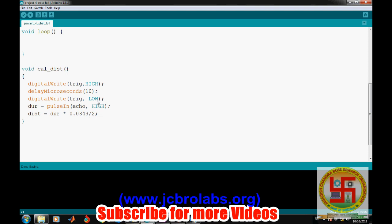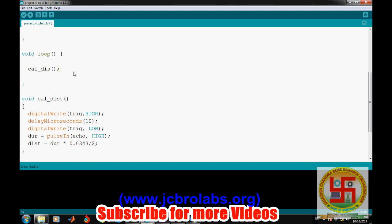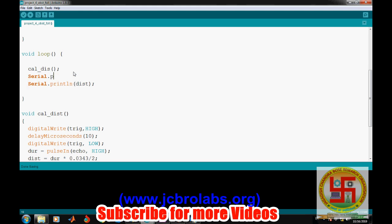Okay, so now we will call this function in the loop, and then we will print it out on the serial port. So let's call this function calculate underscore distance. That's it. And then we will print serial dot println distance calculated in centimeter, and then serial dot println distance, in order to let the user know what we are calculating, and then we will provide a delay of 500 milliseconds. So at an interval of 500 milliseconds it should keep on doing it.